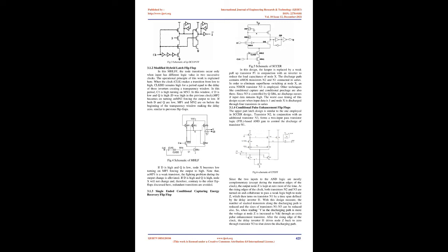Other techniques like conditional capture and conditional precharge are also there. Since N3 is controlled by QFDBK, no discharge occurs if input data remains high. The worst case timing of this design occurs when input data is 1 and node X is discharged through 4 transistors in series. 3.1.4 Conditional pulse enhancement flip-flops.